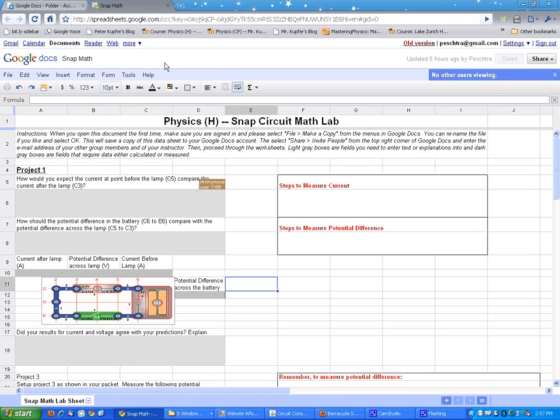The small current ones usually only measure up to 250 milliamps. So times that we're going over that, we would obviously need to switch up to the large amp pole, which will be the first experiment we're doing, will be large amp poles.